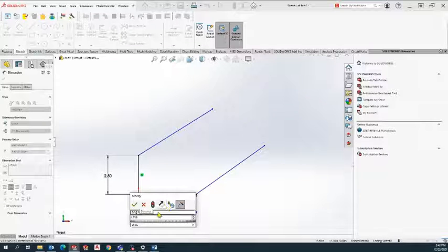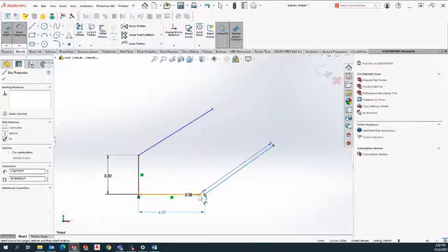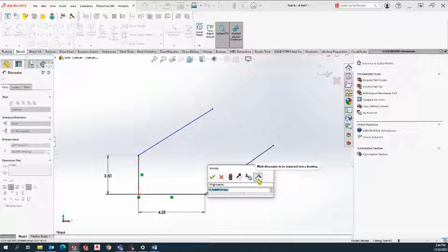There. So now you can always hit the checkbox. Now you see how that automatically grows for you. You know, SolidWorks has that intelligence that you can do that. It does follow through on what you need. You can then pick these two. If you notice, it is a smart dimension, and it actually puts the dimension number for you, and it picks it, and it knows it is an angle. So that's what makes it really intuitive.